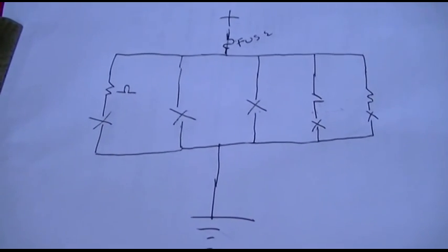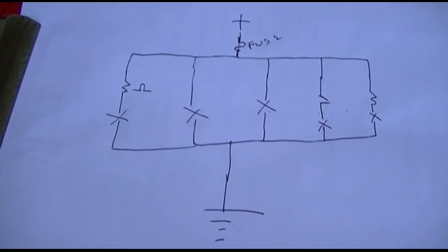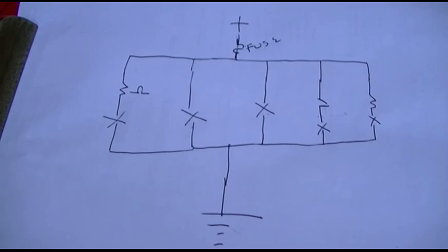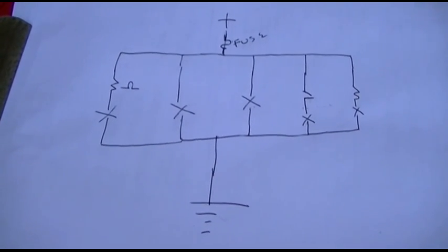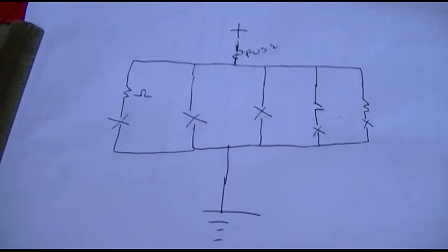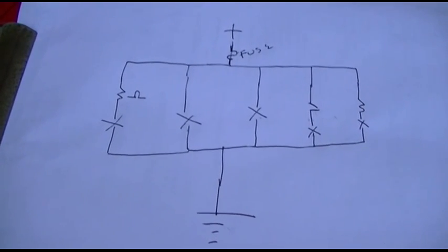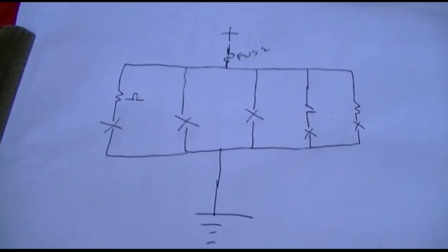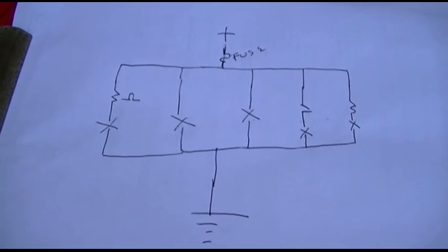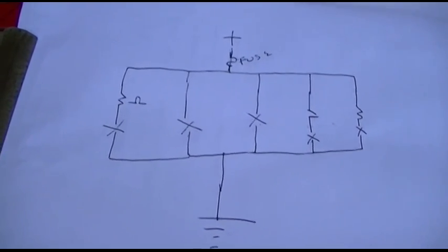That works too. But you really don't want to do that unless you have nothing left to lose and are just completely out of options. Sometimes you get carbon tracking or something in the circuit board and you just can't find it, and you almost have to let it burn and smoke so you can locate it.